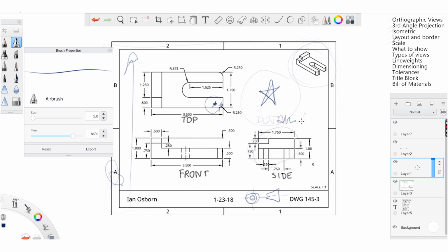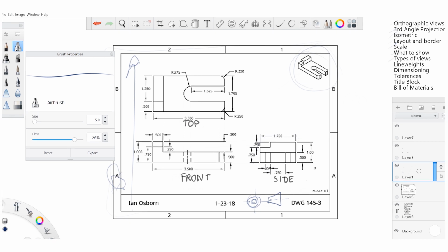Please note that you should always be drawing and writing in capital letters on technical drawings as well. Just keeps it nice and consistent and clear, and it is a standard thing for technical drawings. Your outer line of each drawing should always be the thickest line weight. So for example, we might have a line like this for an outline, then these inner lines, which you can see, which represent this length here, you're going to have this slightly lighter, so that they can see that this isn't an actual outline, but it is a defining line of your product.